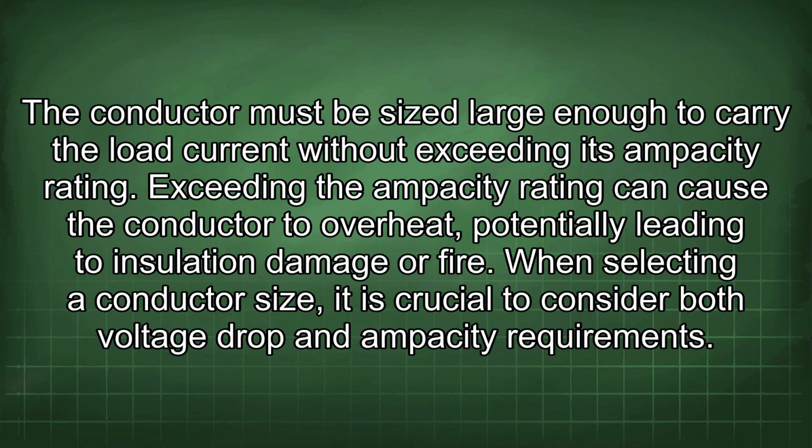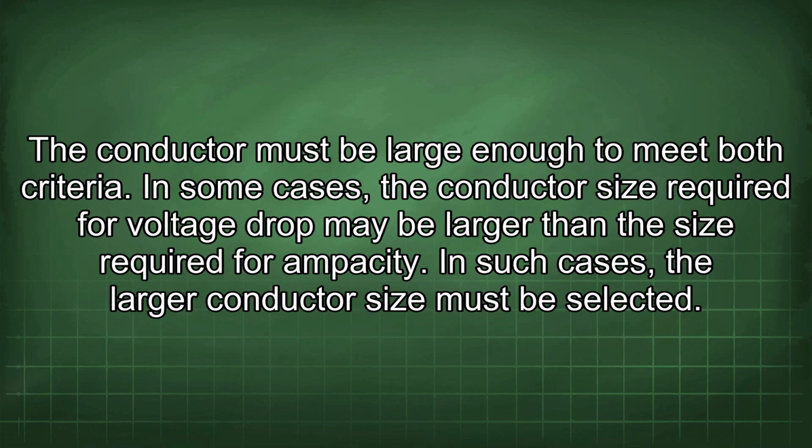When selecting a conductor size, it is crucial to consider both voltage drop and ampacity requirements. The conductor must be large enough to meet both criteria. In some cases, the conductor size required for voltage drop may be larger than the size required for ampacity. In such cases, the larger conductor size must be selected.